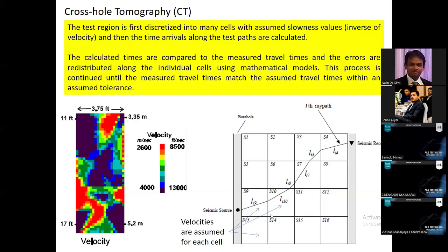Okay. So once you get the velocities, it will show as a velocity profile like this. So you can see small squares, right? Small squares indicating this kind of segments. So each segment, once the analysis is done by using multiple wave records, the software can calculate the wave velocities for each region like this, right? So low velocities indicate a defect.